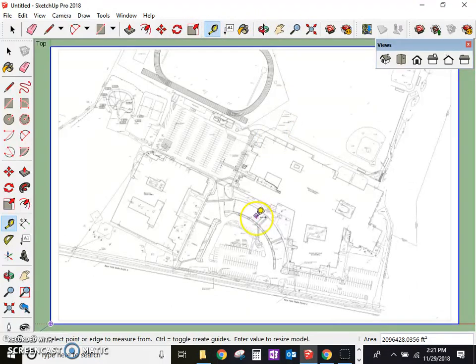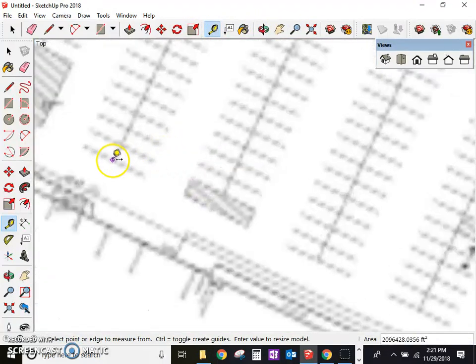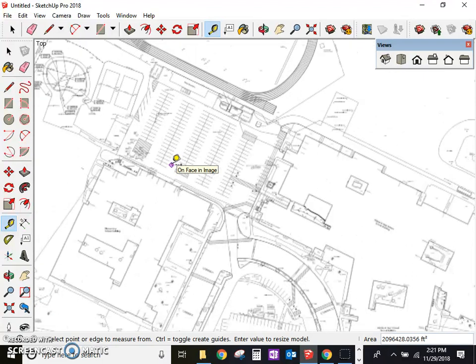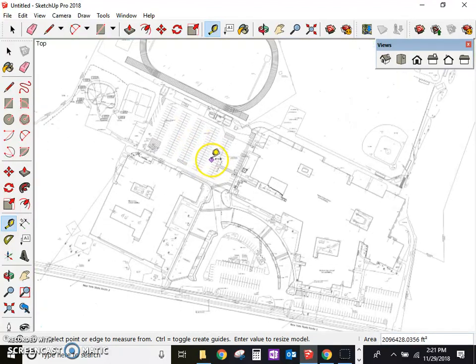I resume extents. So now when I go in here and I measure a parking space, I get, see that? 9 feet roughly by 18 feet roughly. It'll be close. You can get real particular with this, but this will put us in the ballpark. So our goal with this, now that we have our site plan in here, is to make a logistics